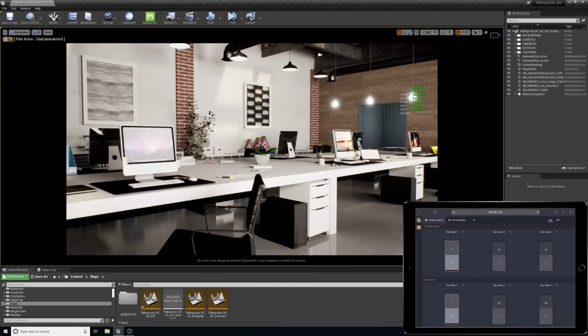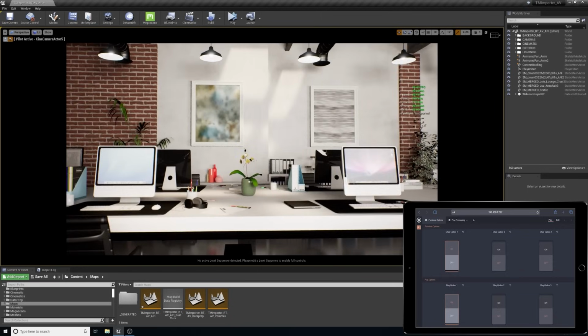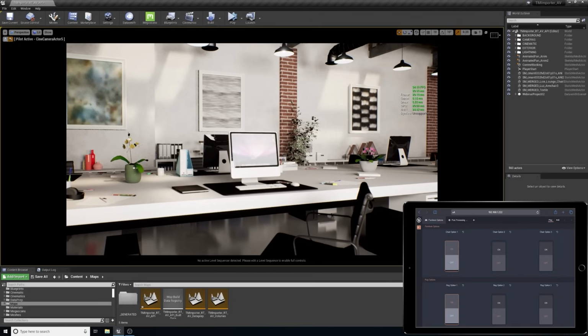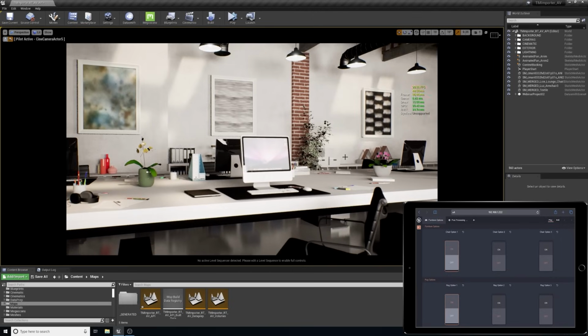So you'll see that I have my iPad pulled up here. The remote control system makes this possible by running a web server inside the Unreal Engine that services WebSocket messages and HTTP requests by remote web applications through a REST-like API. So you can operate the engine remotely from a different computer or mobile device that is connected to the same network as the computer running Unreal.